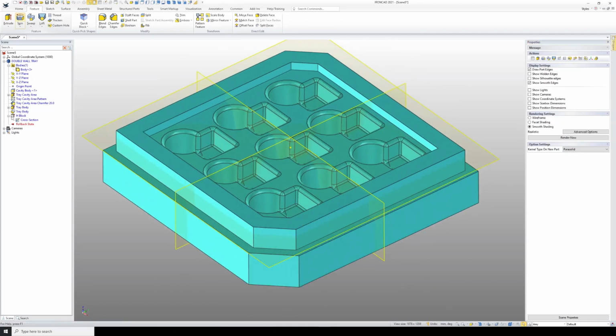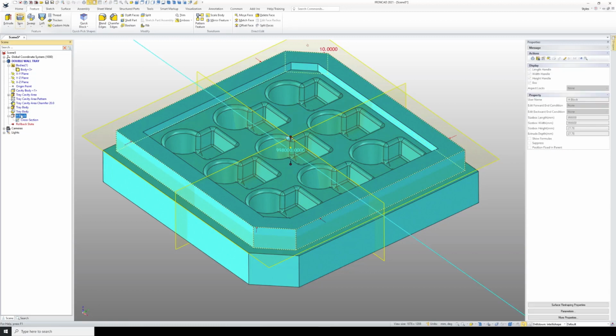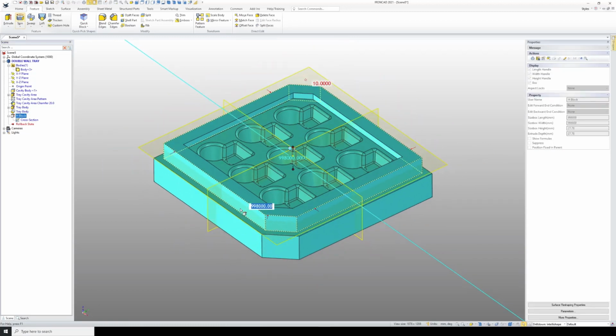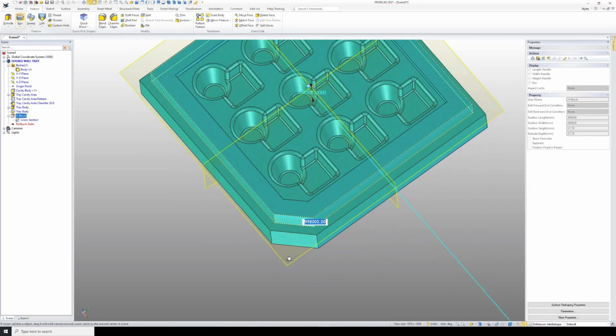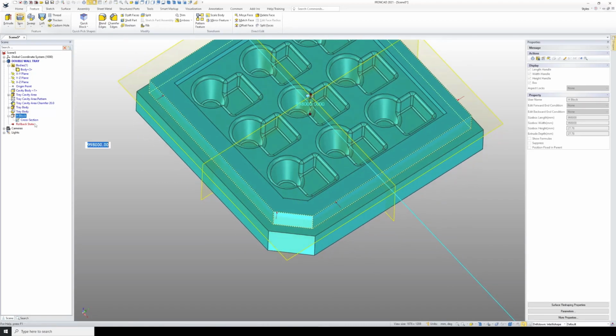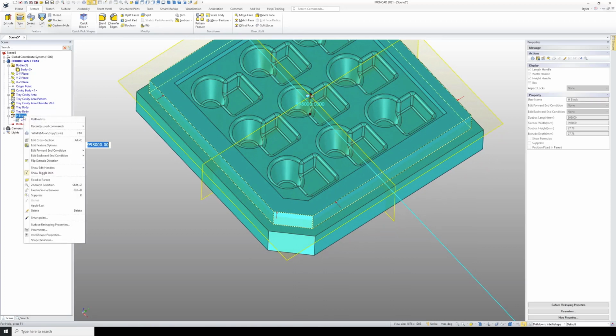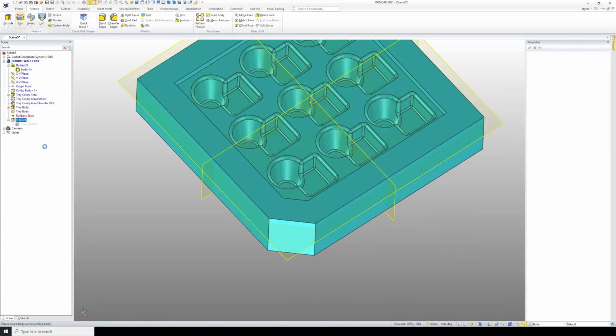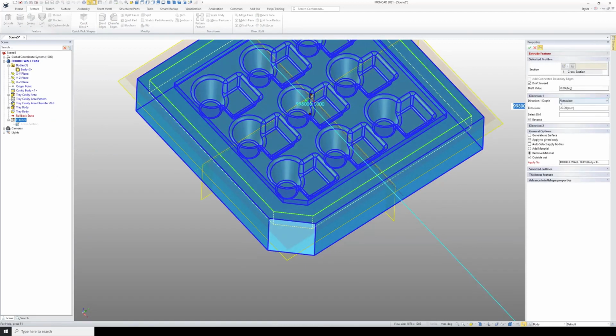Now regarding the depth, what I want it to do is I want the depth of this cut to match the depth of my cavity here. So I'm going to go back to my extrusion here and my edit feature, and so whereas I've got a distance here of 27mm at the moment, I'm going to select up to surface.